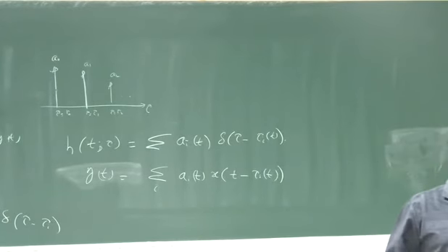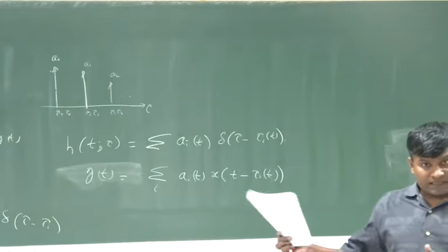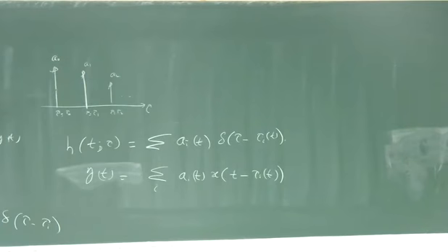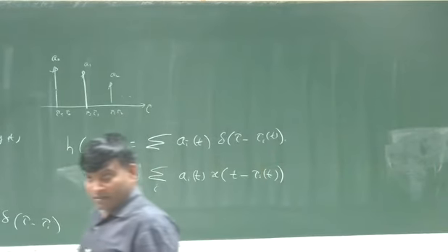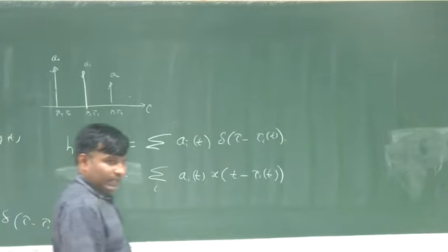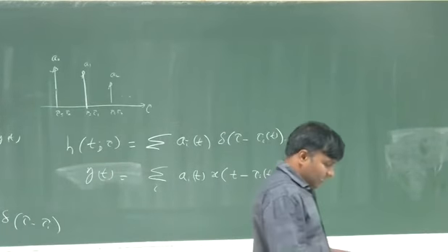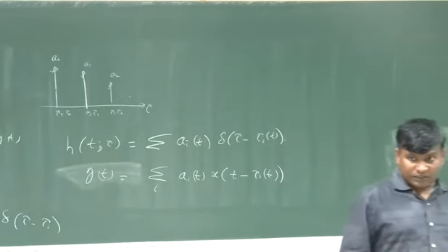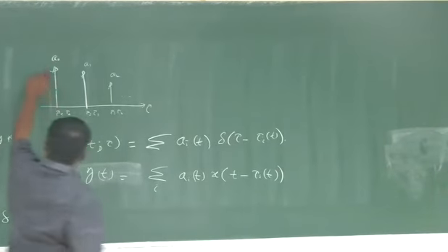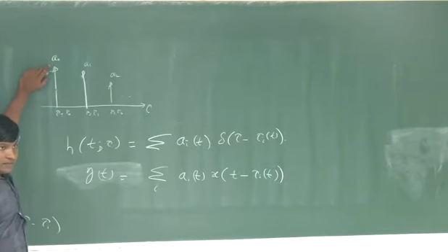Typically we measure the impulse response in any system not at passband level. We always carry out all the operations in baseband, low pass. Most of the time we work with that. That being the case, we also want to know the impulse response in the baseband form. Right now, this is what the channel looks like.